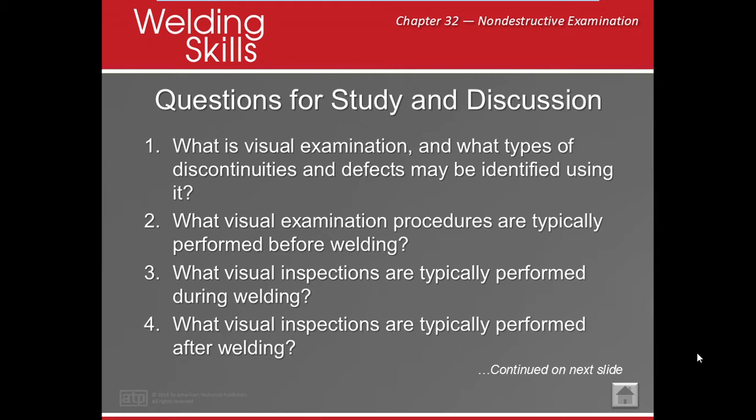What visual examinations are typically performed during welding? All right, guys, we know that we have a hold point. That's a big one. Preheat and interpass temperatures, okay? As well as examining your root pass and probably some of the other passes that are going on.